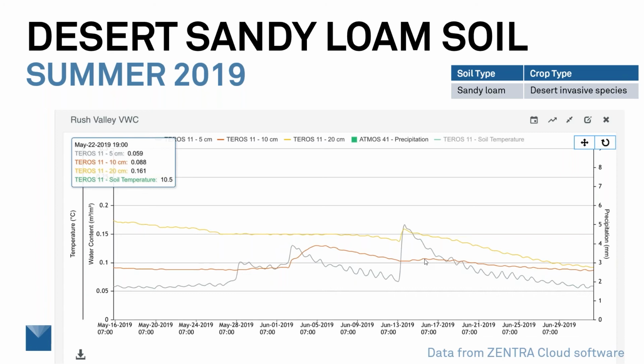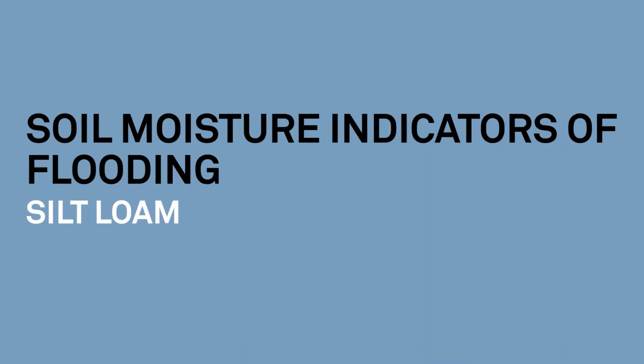Water actually moves in the soil in fingers, and there have been a lot of studies to show that with dye tracers, that in fact it doesn't just go as one giant block, but it comes down in fingers into the soil, and it's likely that one of those fingers reached down and maybe went to this 20 centimeter sensor and wasn't necessarily quite as connected to this 10 centimeter sensor. So I'm not surprised to see that, but I will be watching this over time to make sure we do get consistent infiltration in those 3, to make sure there's not some problem with infiltration above that 10 centimeter sensor.